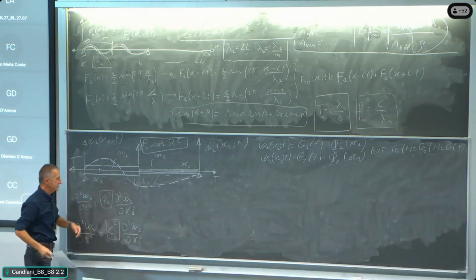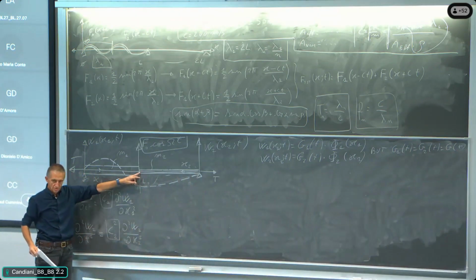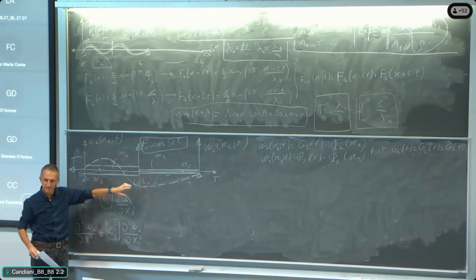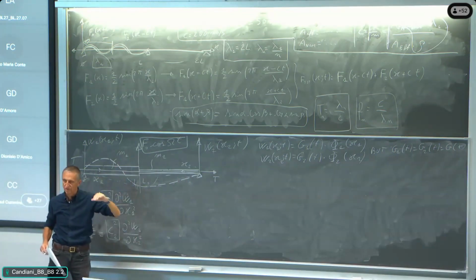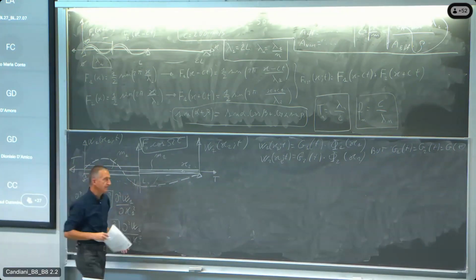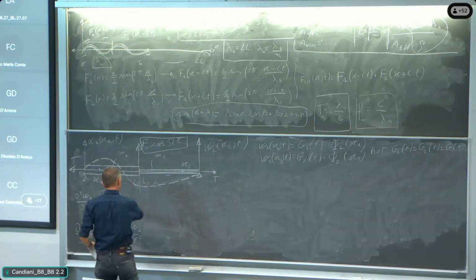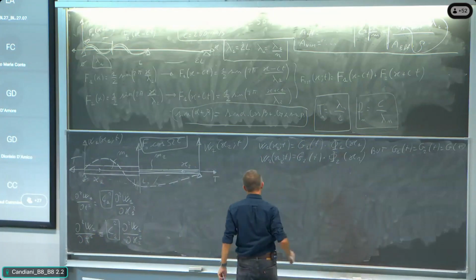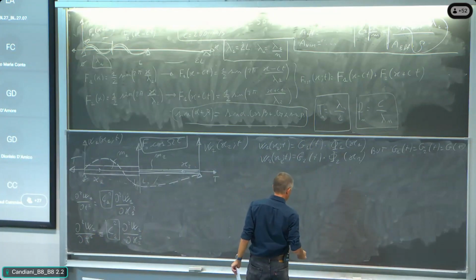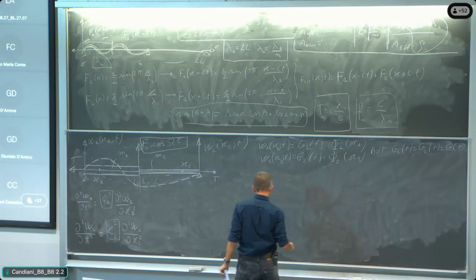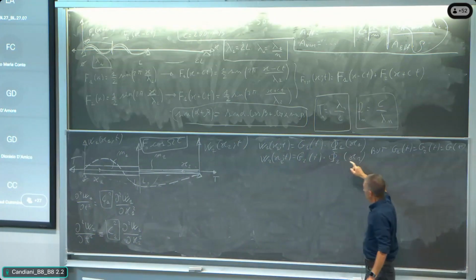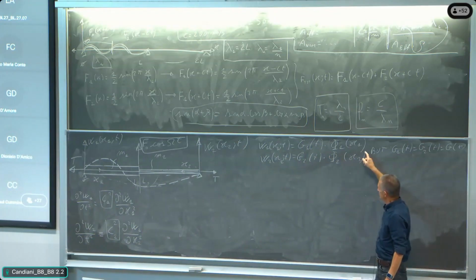The time function is the same because the two bodies, the two domains are sharing one section. In that section, they are moving exactly the same, so the time function cannot be different. It must be equal. And so in order that those functions are satisfying the partial differential equation, we are using the separate variable approach. And so we are saying that the two functions are given by the product of the time function times the space function.